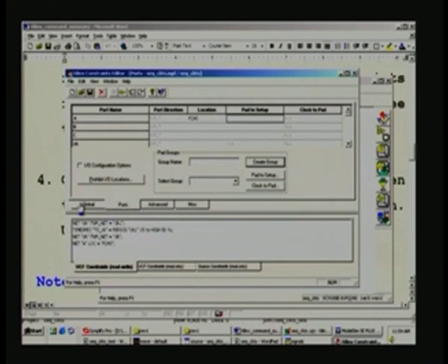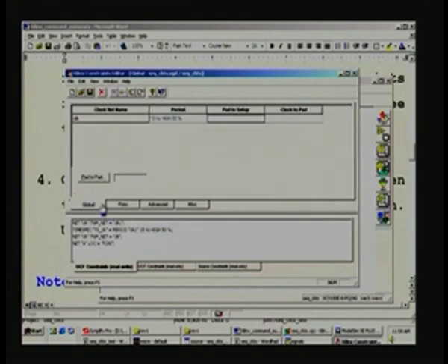If you click on this, you have Ports here, and you have another thing called Global here, and it is here you have to mention the actual clock. It lists 15 nanosecond high, and I had changed it in between, that is why it was like that. Now I will change it back. I will remove that 1, and it is 5 here, just enter. That is what we have written on that command summary, and immediately this 5 nanoseconds has taken effect. That is how you change the frequency.